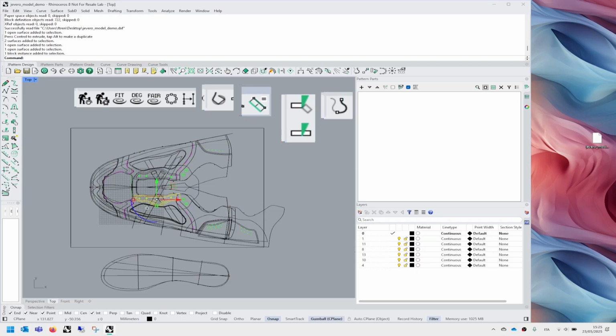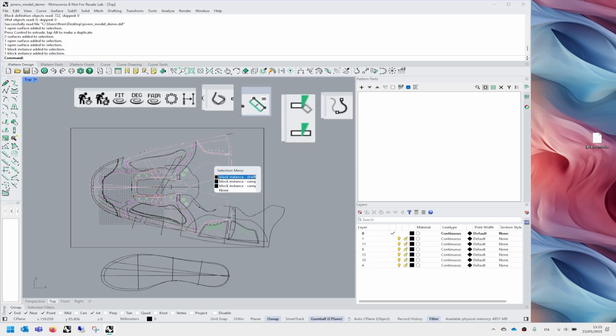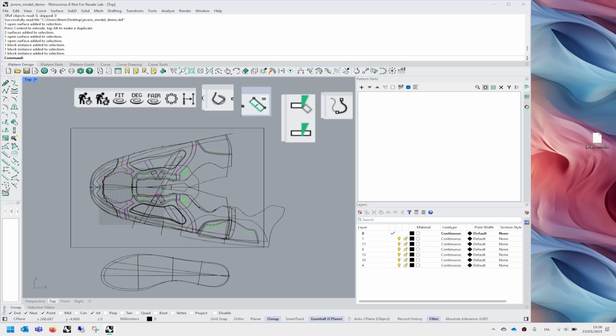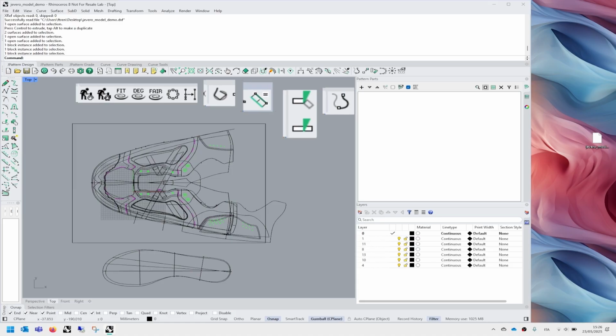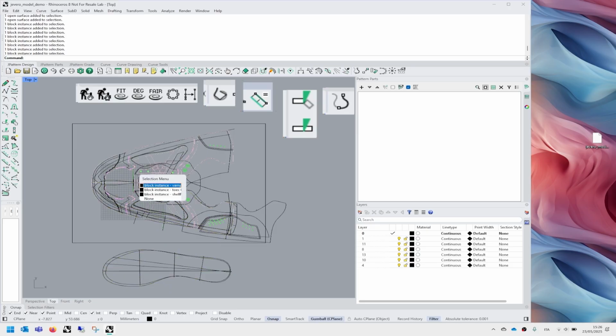Whenever you select an object, you clearly see that you select a group of objects that have been saved as block definitions. That's because some programs export by default in this way. So we select by just clicking one thing, we select a group of objects, which is alright, but we want to touch the specific curves to start rebuilding and reconstructing the whole model.